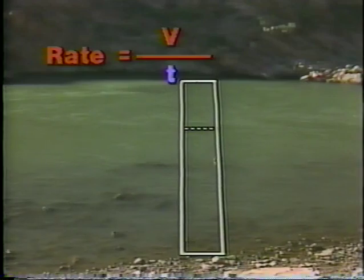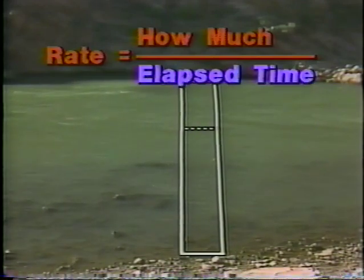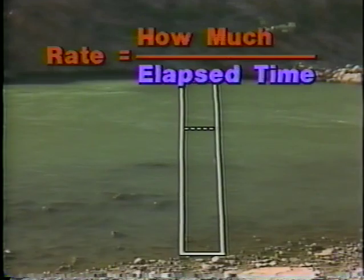Then mark where the stick lands and see how far the stick moves in a period of time. Now you have a length, a width, and a depth. This is a volume of water that moved over that period of time. Volume over time is the flow rate. In other words, the flow rate of a fluid system is how much fluid moved over elapsed time.